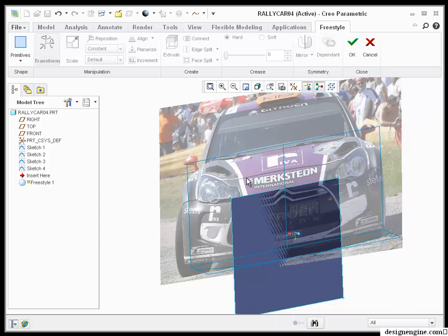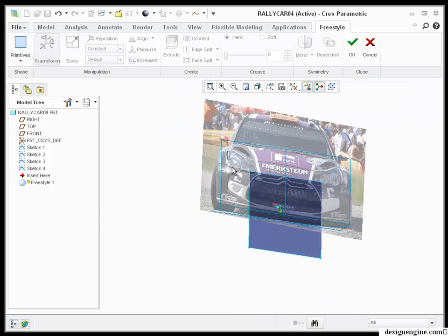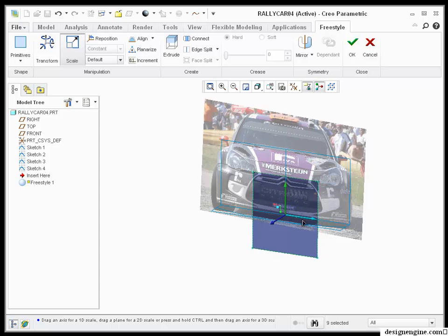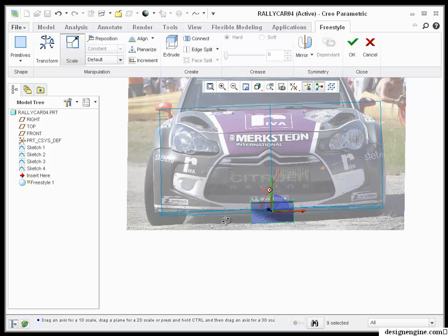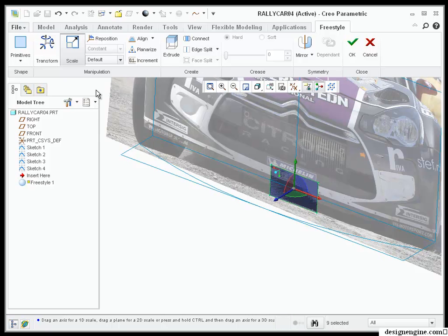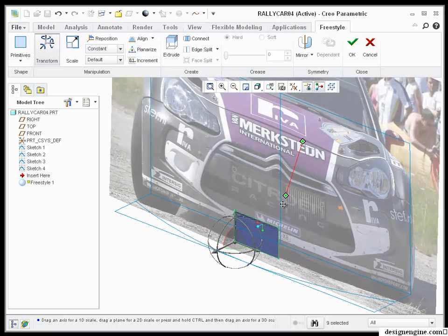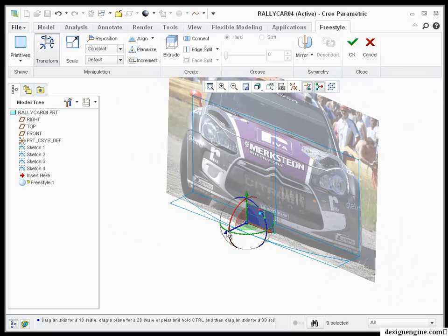I'm going to go ahead and create a polygon plane. I'm going to scale the plane down using a wide variety of tools that we have available. I'm using the control key to size the geometry smaller. Okay. Now I'm going to move the entire geometry over using transform. We've been teaching Sub-D type modeling tools at Design Engine using Maya for over 10 years.